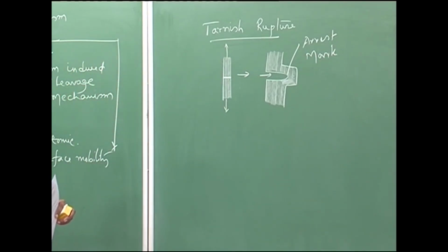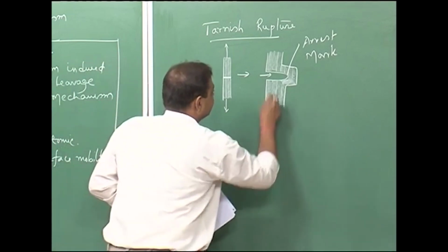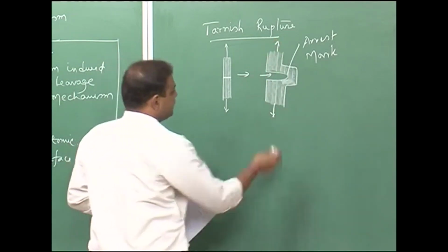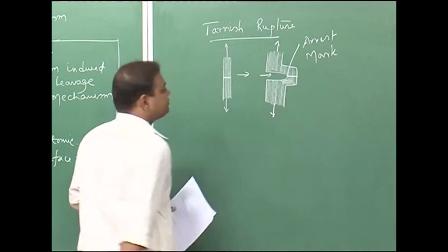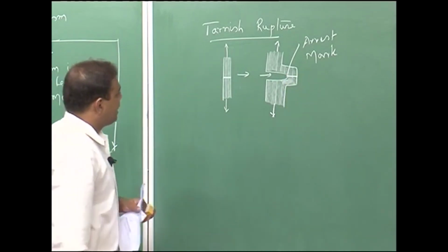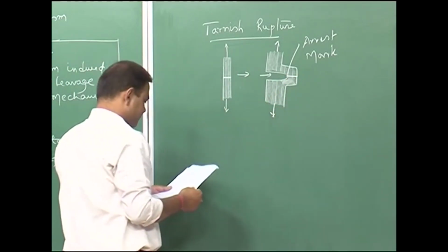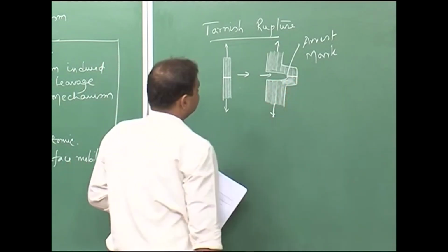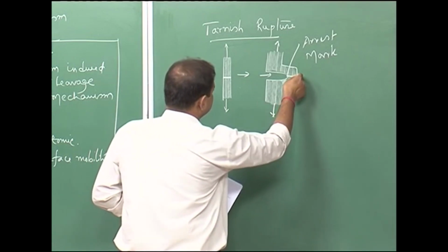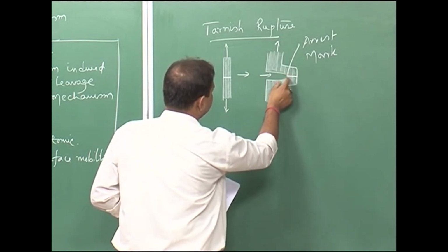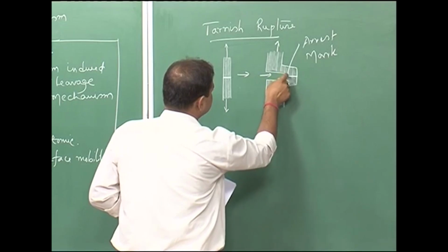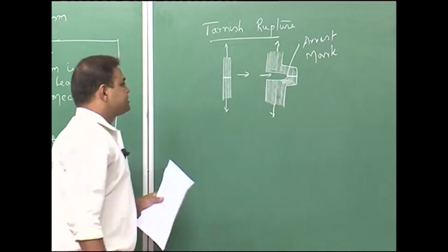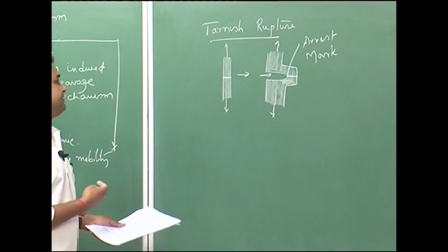Now, the second step, again this is under stress. So, again you can have a small crack formation here, and then the crack is experiencing the tough matrix. So, it is getting stopped here, and also you have the crack blunting, and this metal surface is exposed to the solution, and again passive film forms.